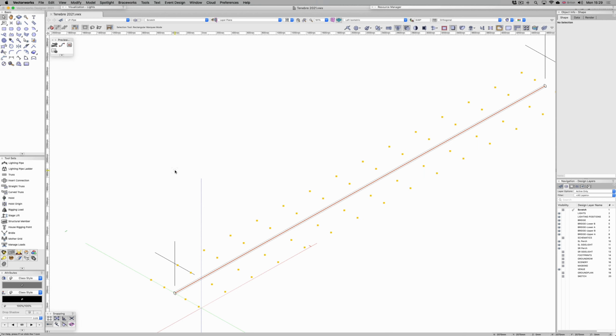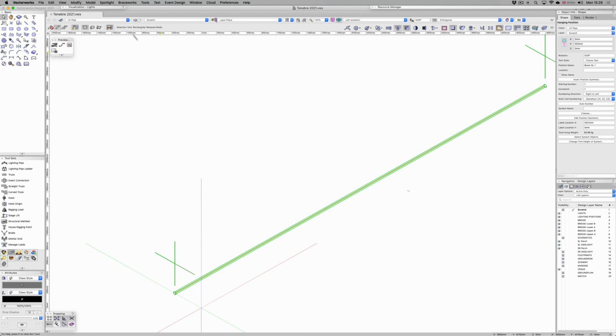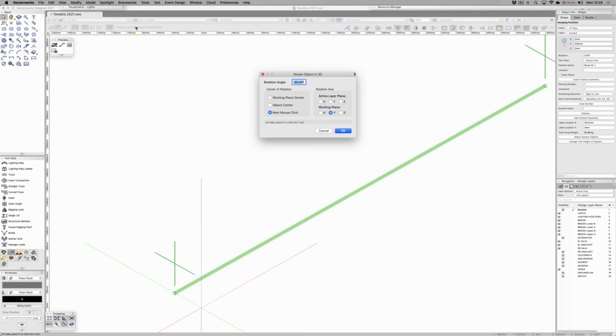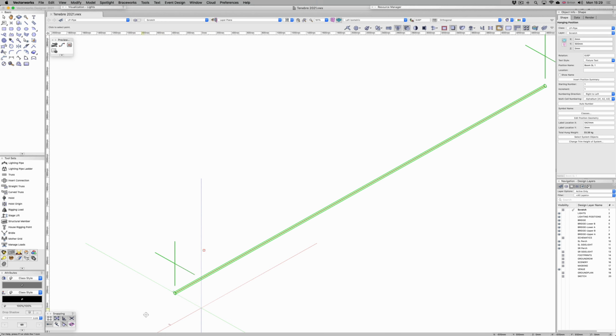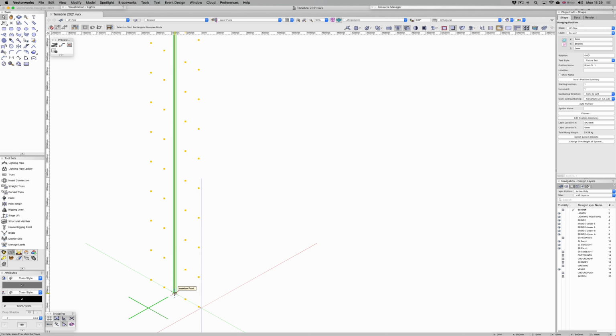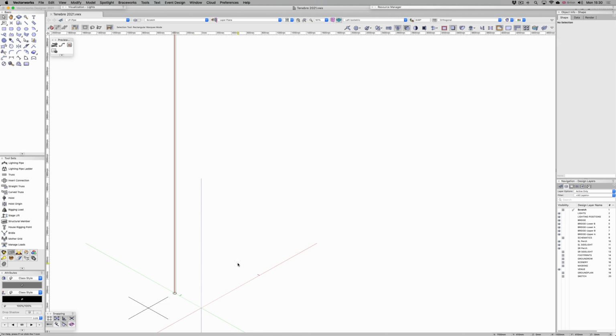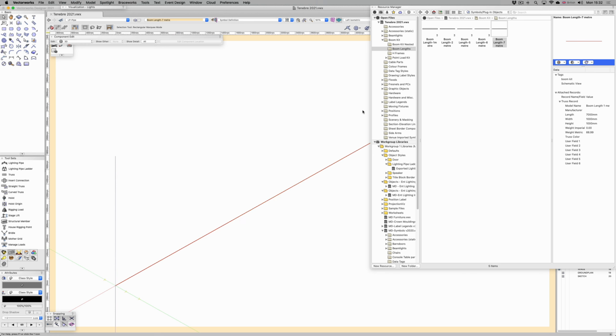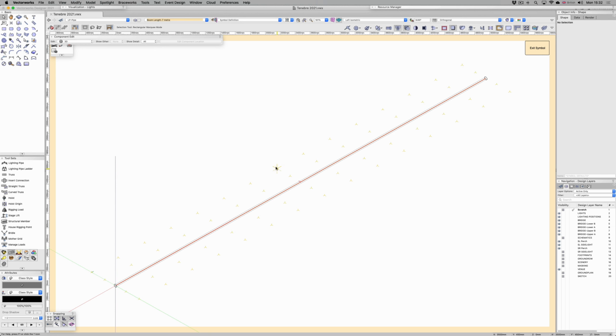Finally, my favourite option is to incorporate a truss symbol into a hanging position. Rotate it up and load it with lights and rigging point load objects in the usual way. I've made my own 3D boom truss symbols with master snap points at various useful sidearm spacings, as well as a NURBS curve down the centre, which helps me with locating snap points for lighting devices.